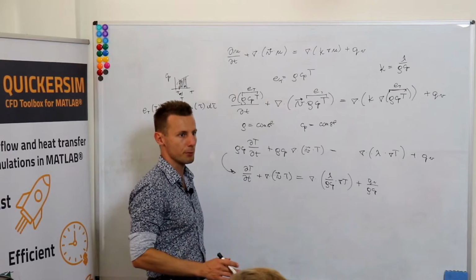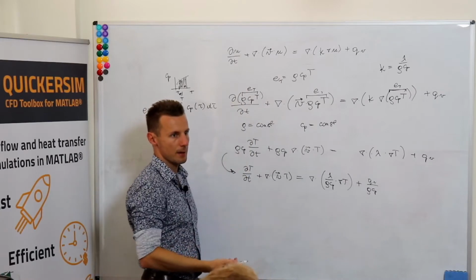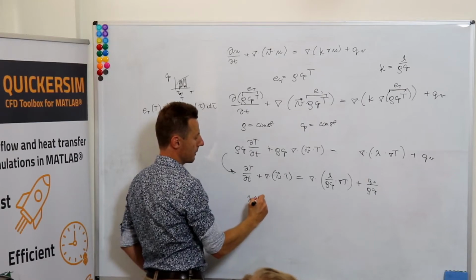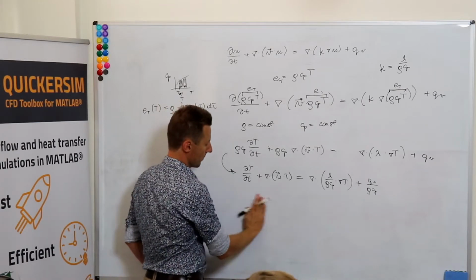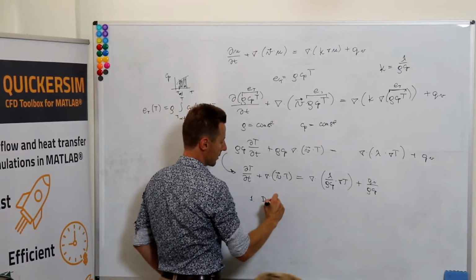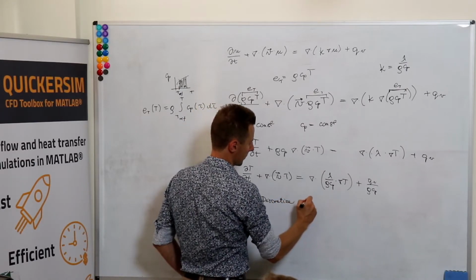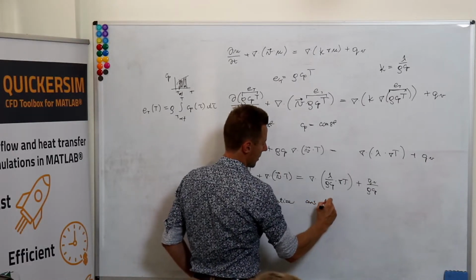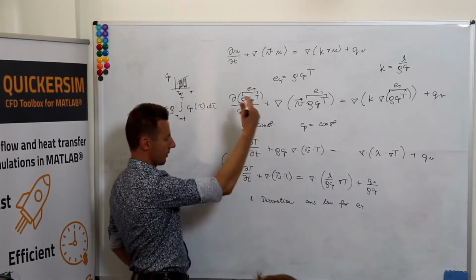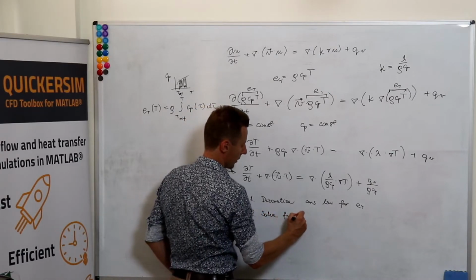And obviously, it does not have any direct or obvious relation with the temperature. So what you need to do in the numerical code is to discretize this equation, solve for ET, and then when you need to calculate any parameters, like for example lambda may depend on temperature. So the first step in a numerical procedure would be to discretize the conservation law for thermal energy, then solve it. Solve for ET.